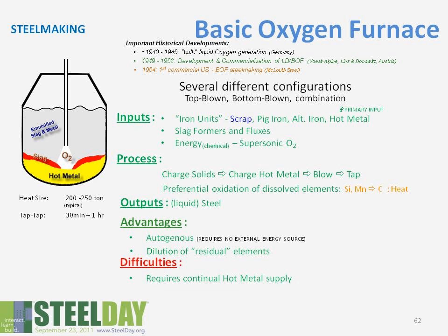The advantage is it's autogenous. Again, we don't have to add any additional energy. And even though scrap is used, it's typically only around 25% of the burden. So we do get dilution of residual elements. The difficulty with this is you must be connected to a hot metal supply.